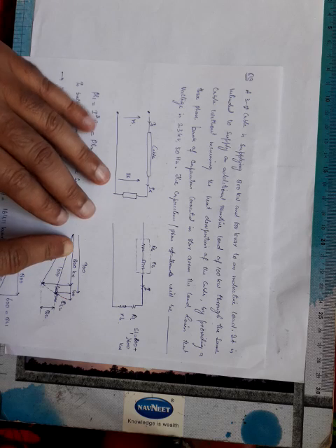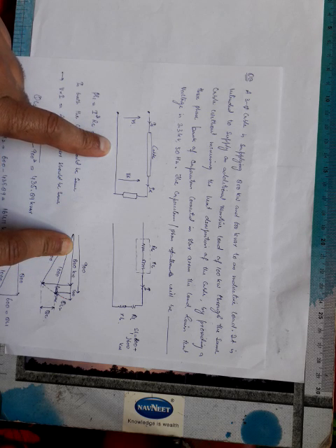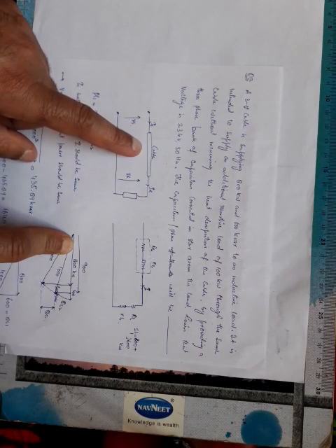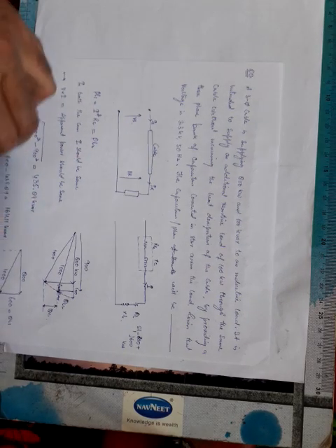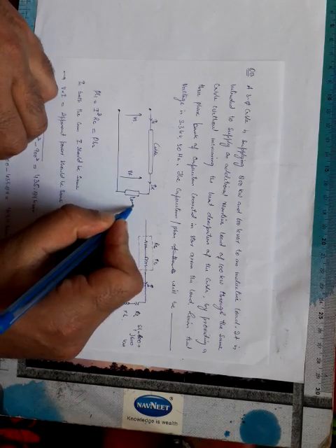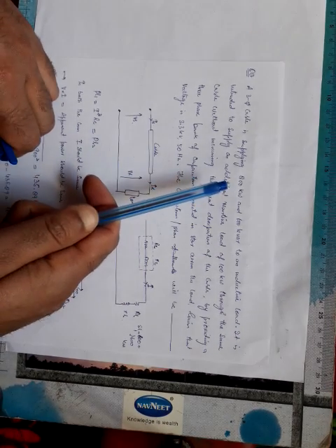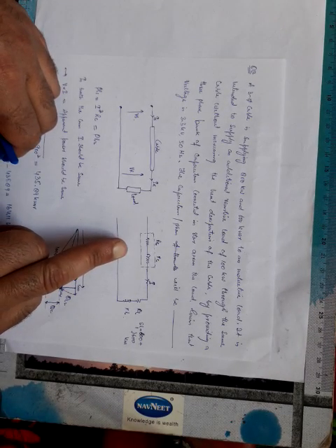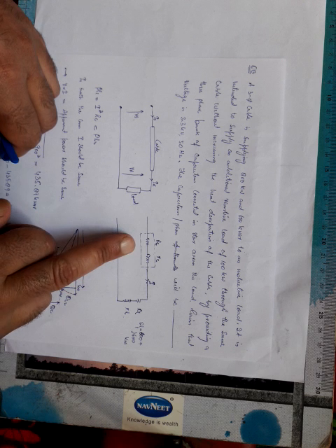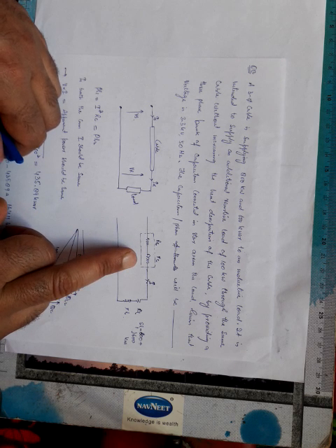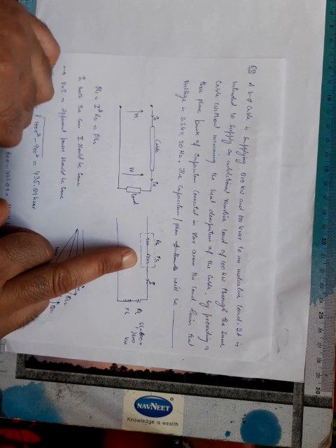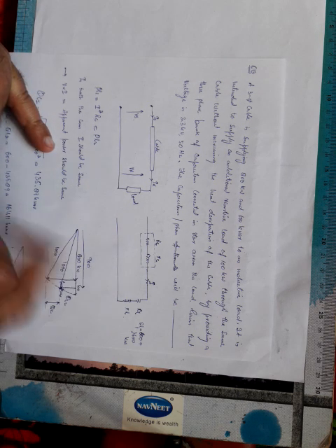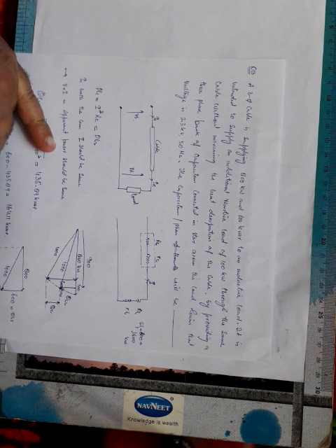First, the load is like this. This is a per phase circuit of the same system. Here is the source voltage, this is the cable through which the power is transmitted, and this is the load, which is 800 kilowatt plus 600 kVAr. Now this is the equivalent circuit, where RC represents the resistance of the cable and XC represents the inductance of the cable. I am neglecting the capacitance of the cable for the time being, and RL and XL are the resistance and inductance of the load respectively.